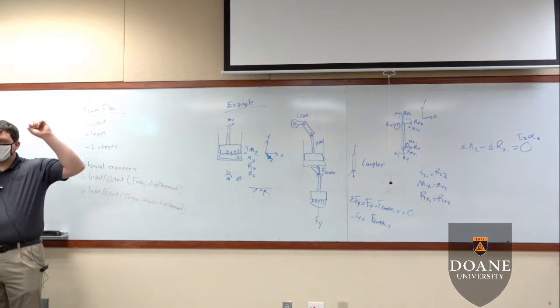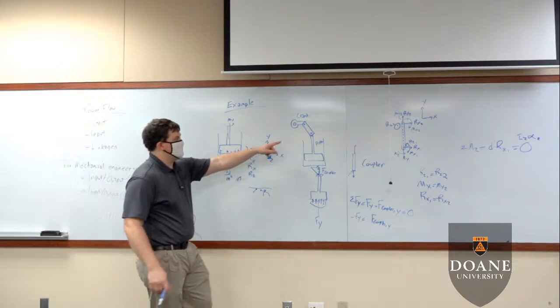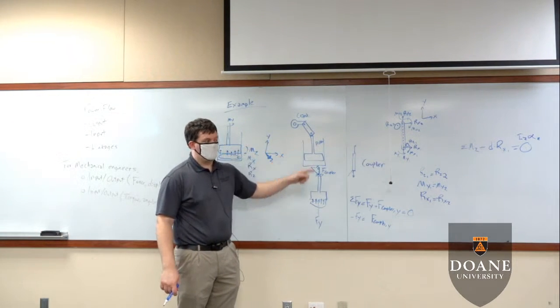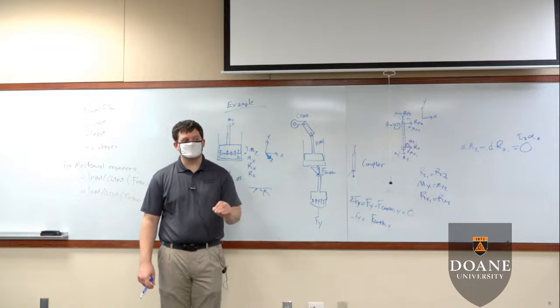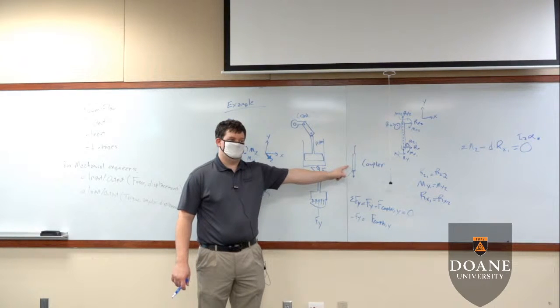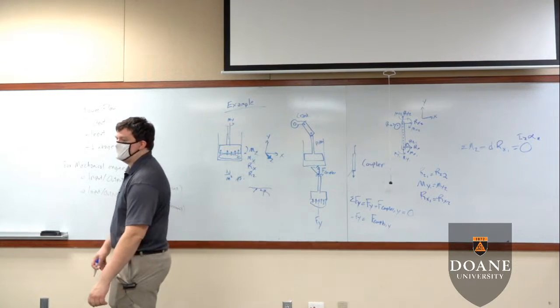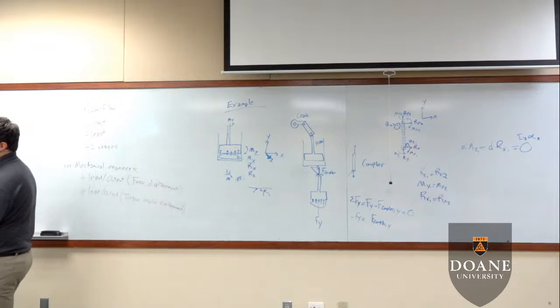Yeah, this is the point where everybody's like, pfft. No, it's true though. The higher the angle is for your coupler, the larger the force is being transmitted through your coupler, just because of this. Because it can only carry an axial force.